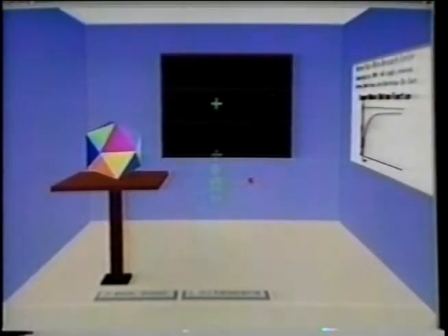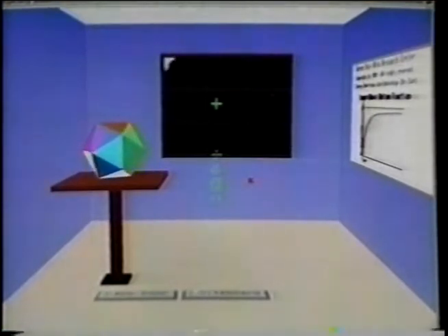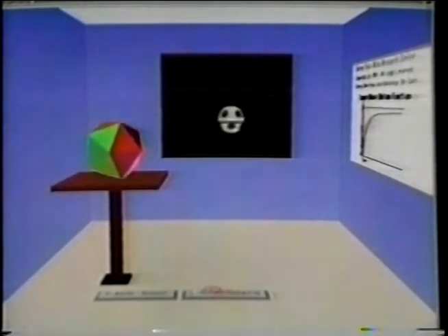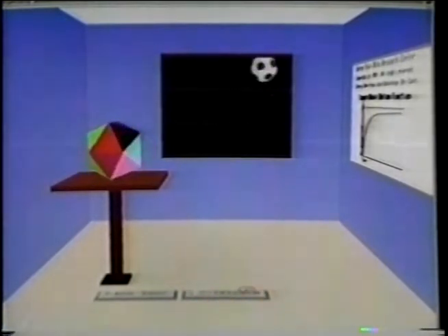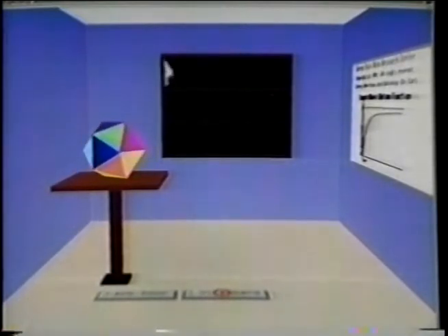This example demonstrates the point of interest viewpoint movement technique. The mouse cursor is used to indicate a point of interest on the surface of an object, which can then be adjusted. The distance to this point is used to calculate a logarithmic motion. With a simple key press, the viewpoint moves through multiple degrees of freedom and asymptotically approaches the object. Another key moves the viewpoint away.